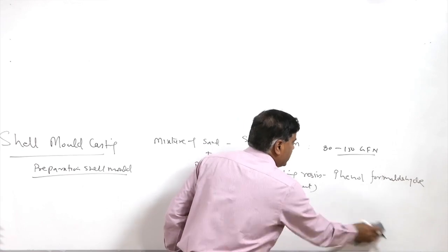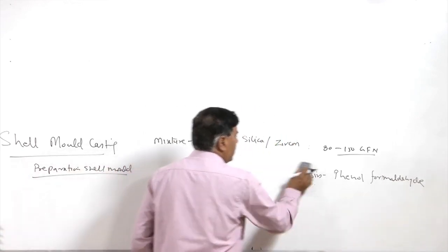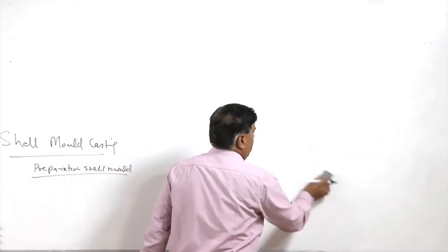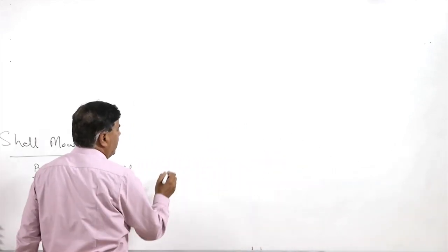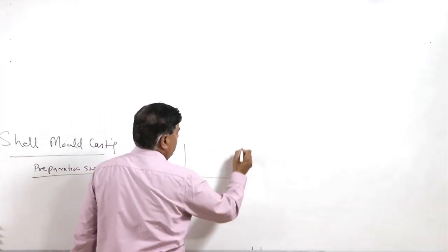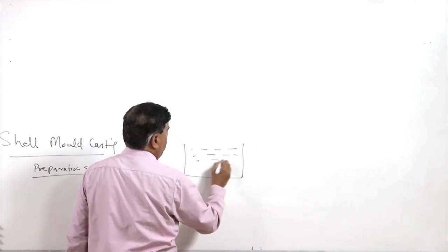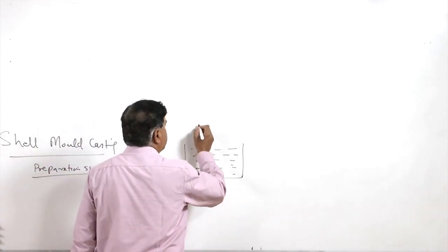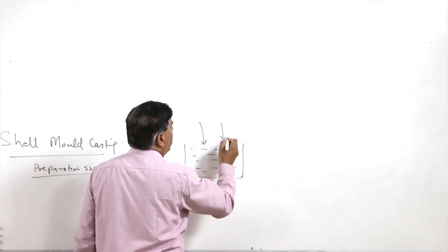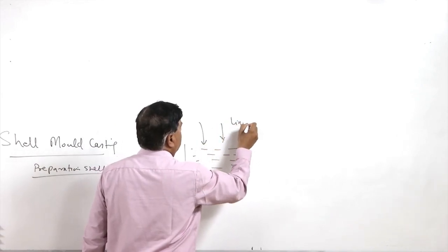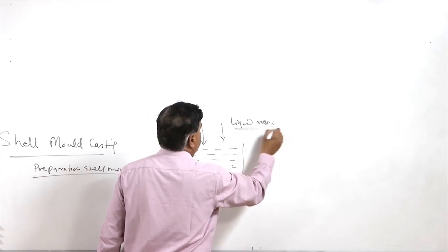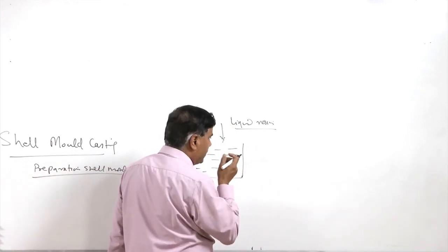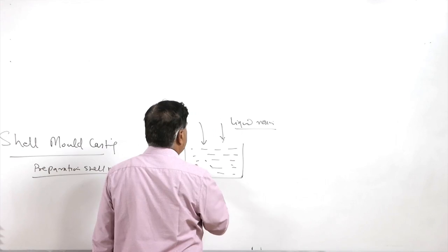So, all this mixture is prepared. In a particular process, dry sand which is free from any clay is provided with the liquid resins, and it is thoroughly mixed with the resins, and the additives are thoroughly mixed in for use.